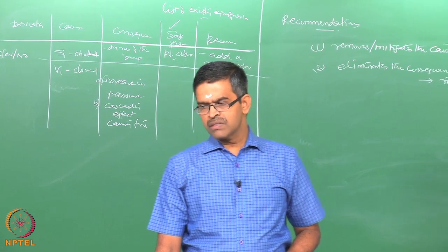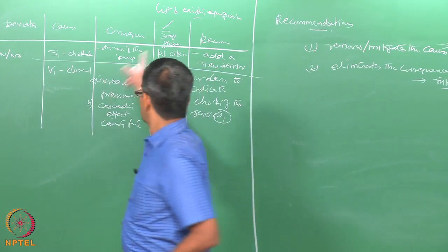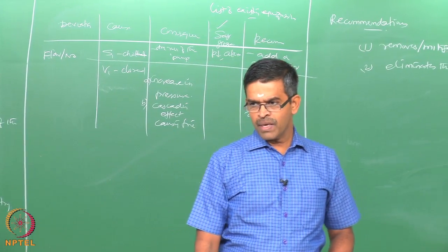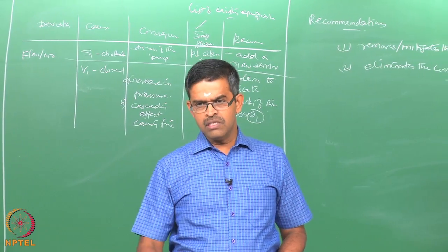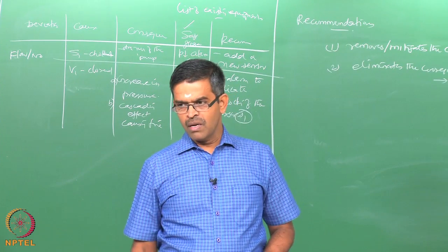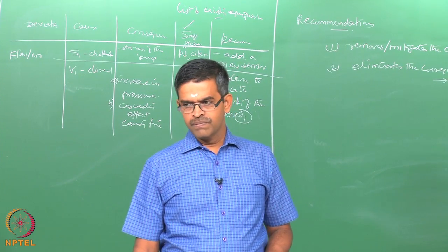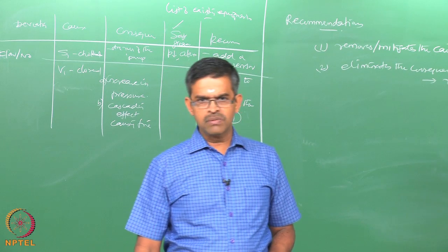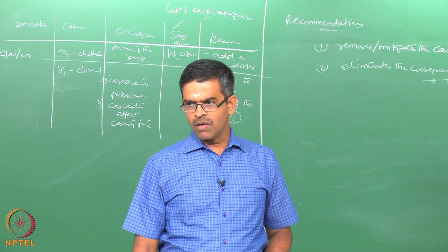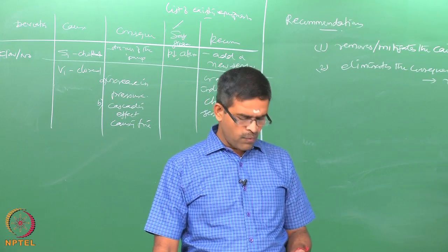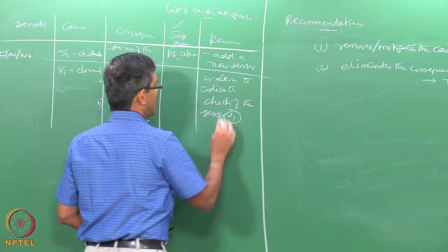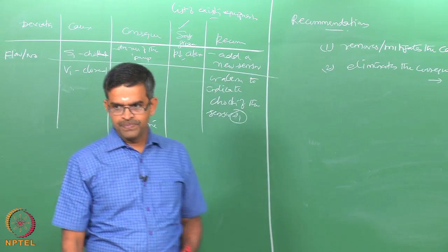So, you must always give regard to the existing safeguard systems available, and account for them working properly. Further, compliance should be considered while writing the Hazop report, like training the personnel and giving proper maintenance. If sophisticated protection systems are added, maintenance becomes equally complicated and expensive, therefore one has to be very careful in listing the recommended actions in a Hazop report.